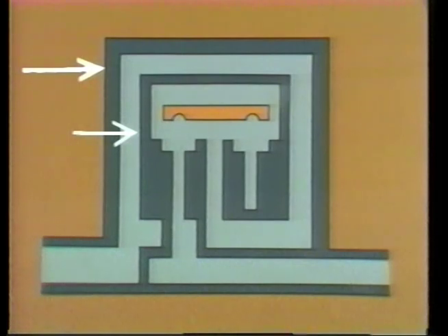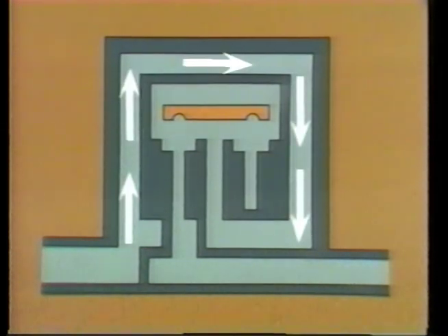Now, some manufacturers have developed traps with double-walled bodies that allow steam to circulate around the trap internals. Now, this maintains even temperature within the trap, even under adverse weather conditions. A metal insulating cap is another way to maintain even temperatures. Now, these caps act like storm windows to hold in any heat, and they have the added advantage of not using any steam while they work. Keeping thermodynamic traps warm improves their efficiency.